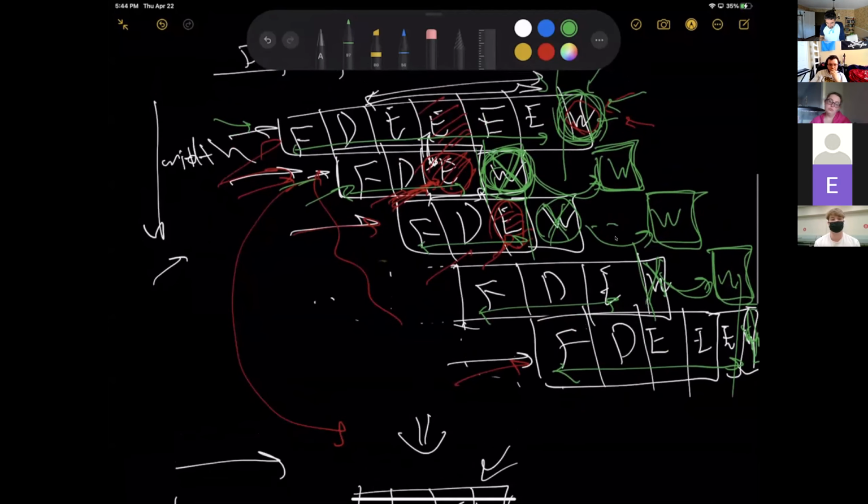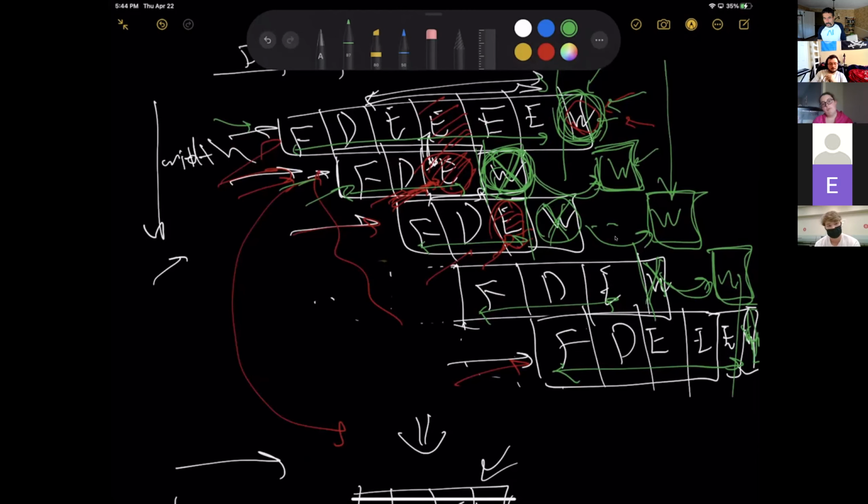So in this case, after we make this change, the architectural state would change at this cycle for the second one, at this cycle for the third one, right? And with this change, you're not violating this property. So basically, you did not violate the property until here, until here, until here. Things went wrong at the write back stage when you changed the architectural state, right?